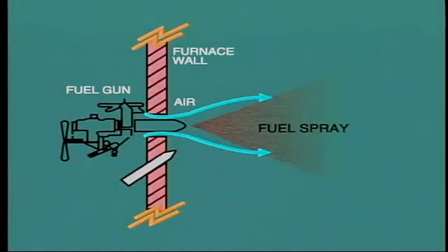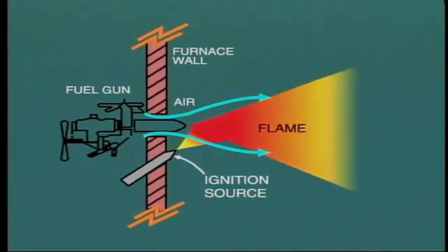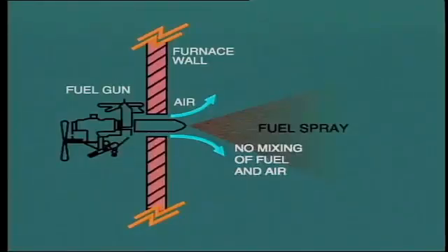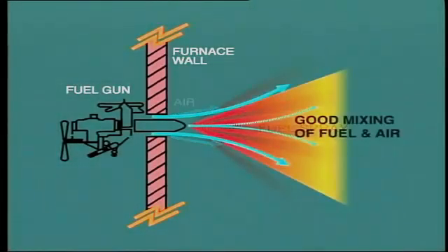In order to provoke combustion, some form of ignition must be provided, usually in the form of a pilot flame or an electric arc. Once the fuel and air mixture start to combust, the ignition becomes self-sustaining and no further help is required. The second item, turbulence, is extremely important. It is vital that the air comes into intimate contact with each tiny element of the fuel. In order to ensure this thorough mixing, some form of turbulence is created as the fuel and air enter the boiler through the burner equipment.